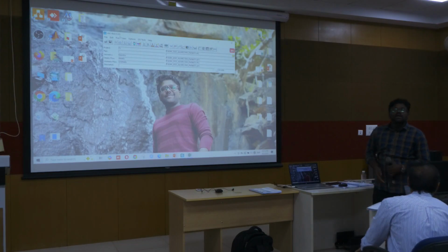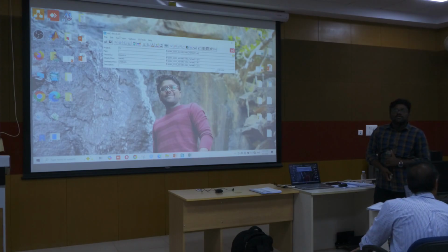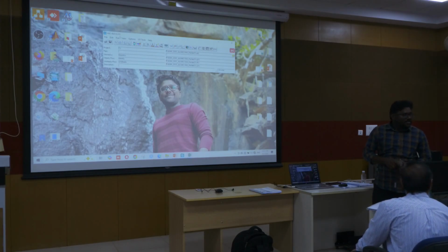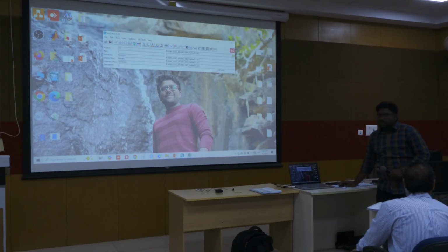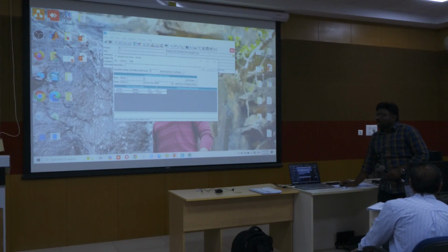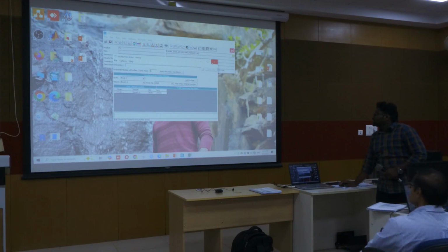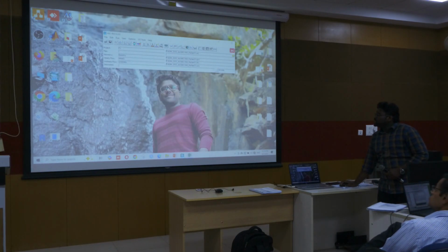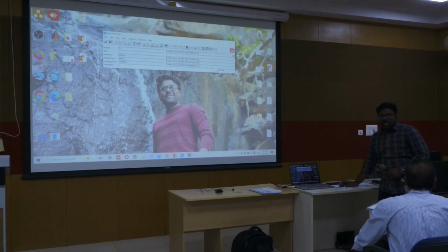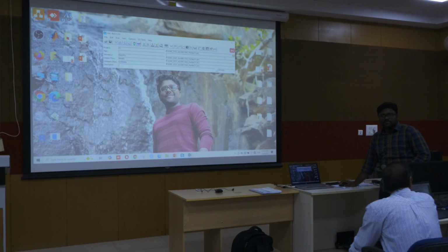Just name what is the steady flow. So to run for the peak, go to edit, click on steady flow data, give the flow here, and then go to file, save it with the name steady flow data. Okay, then close it. See, here in the steady flow it appears.